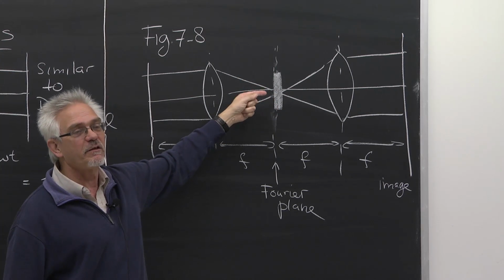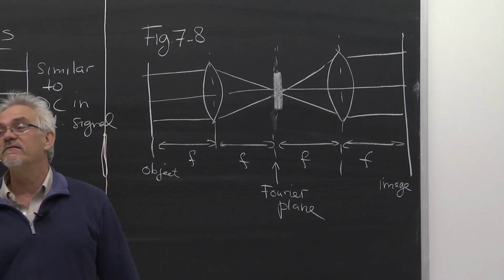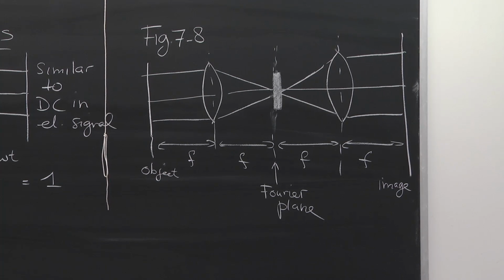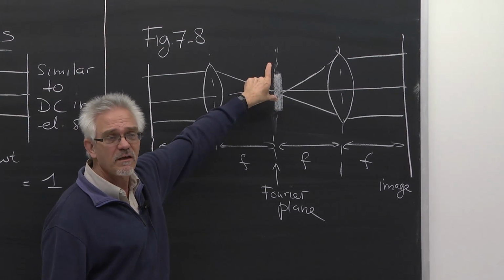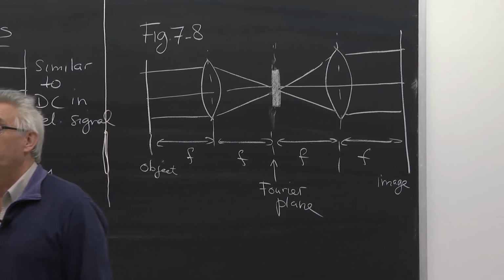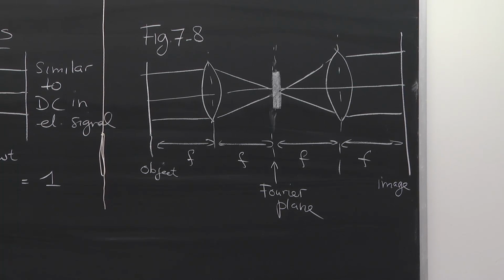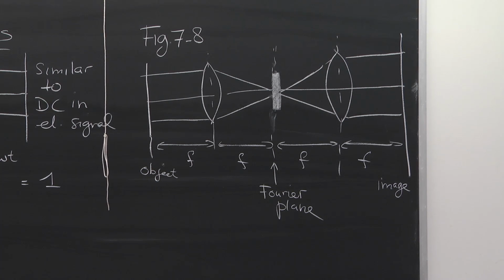So you would, relatively speaking, enhance the edges. Just like in a power spectrum where close to zero you have the low frequencies, that's the same way in this image: close to the center you have the low spatial frequencies. If you remove them, the high spatial frequencies survive, and they basically represent the edges. So you can do a lot of fun stuff. And I actually have an exam question about this too. You can have some fun with that.